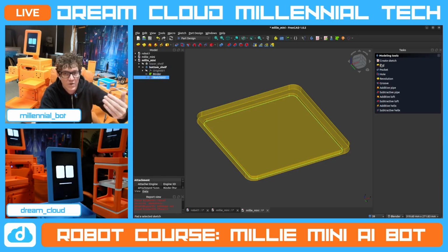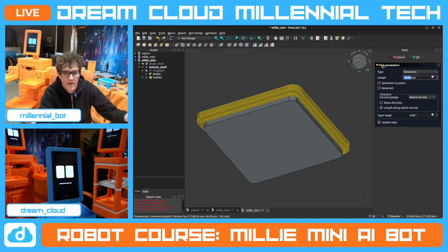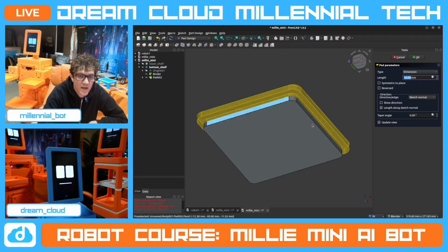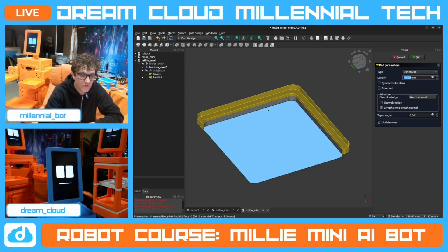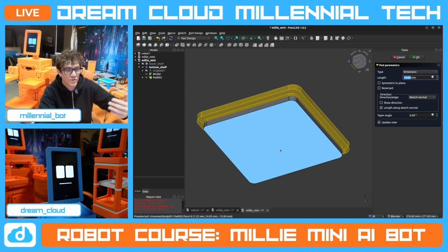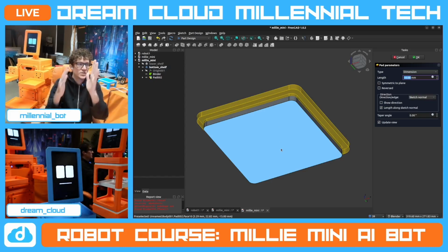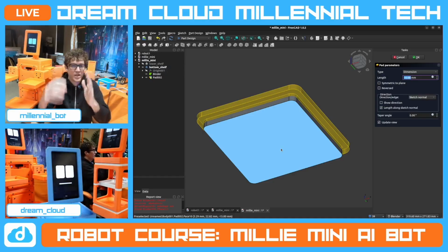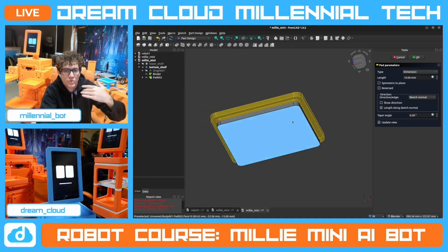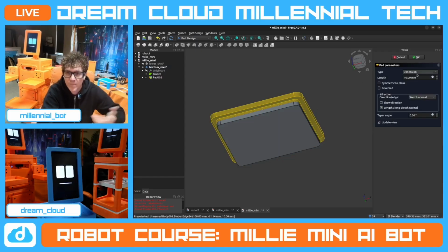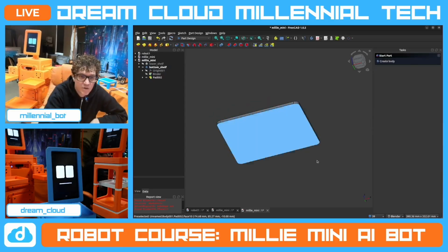And all we have to do is now create a pad, right? So we're going to create a pad. So what is this pad doing? That pad took that drawing on the surface and just moved it in the direction of the surface, right? We knew we were drawing on that surface, so when we made a drawing, we pulled it out. And it just so happened to be the same size. And we don't need to touch the other drawing because we know that it's 180, 180, 10, right? The only thing we have to change again is 5 because we only want these middle ones.